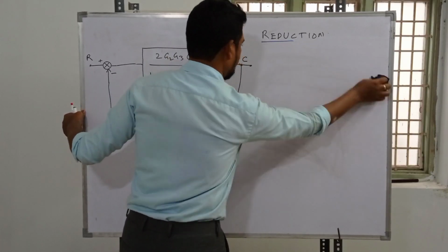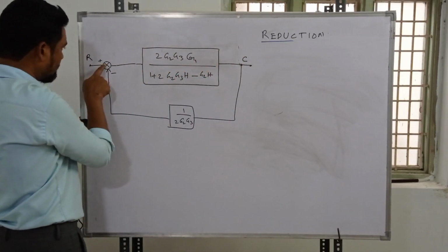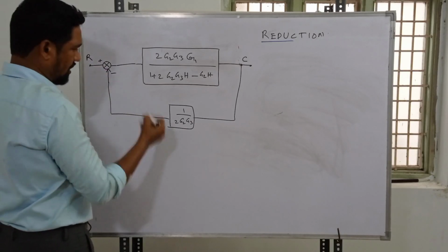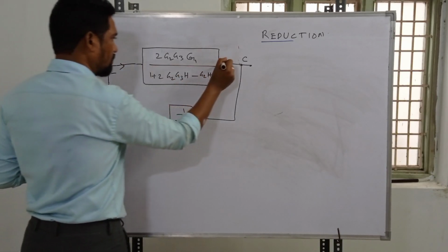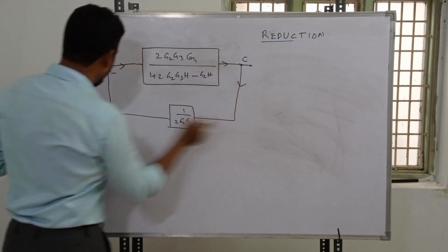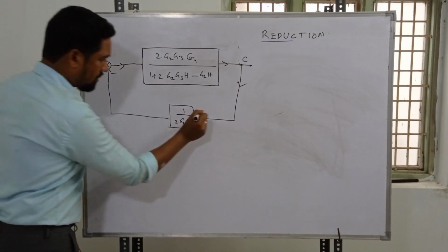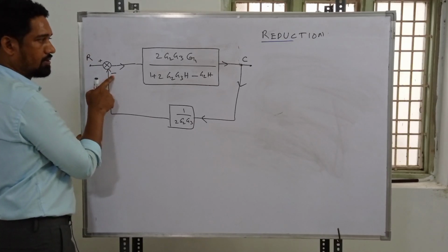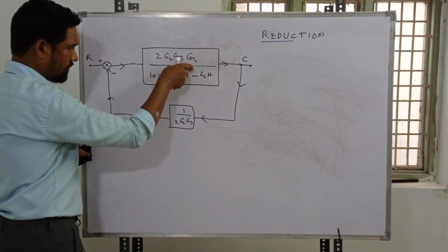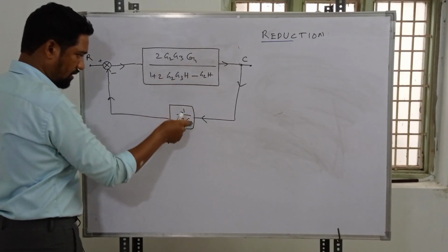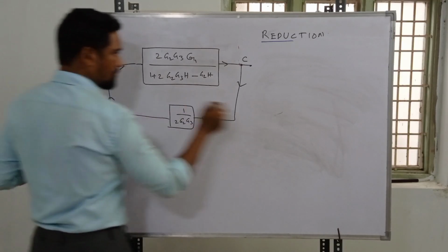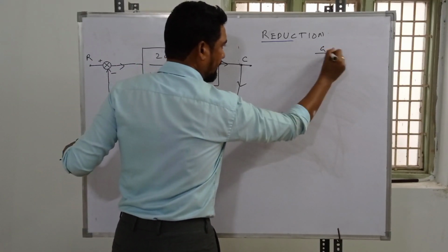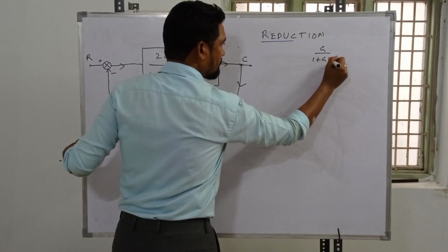Okay, can you see this R? And I forgot to mention the arrow mark over here. It's going, and after this, it's coming back, because we have stuck to this one. Now it's coming back with a negative feedback. So this entire transmittance will be taken as G and H. It's a negative feedback, so this comes into the picture, right? G by 1 plus GH.